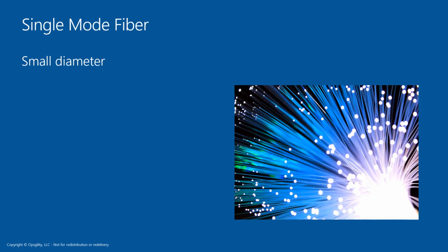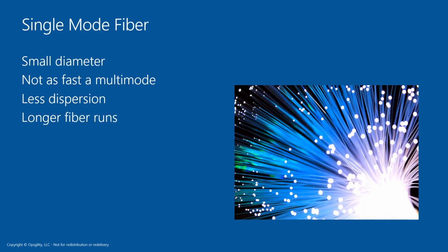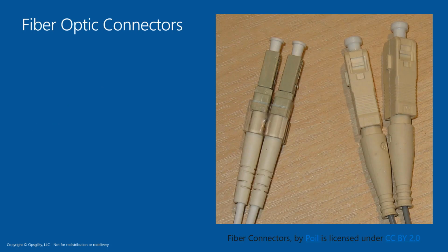Single mode fiber has a small core that only allows one mode of light to propagate. Because of this, the number of light reflections created as it passes through decreases, lowering attenuation, and it creates the ability for the signal to travel much further. In this case, it could go for miles. The application is typically used in long distances and higher bandwidth runs by telecommunications companies, cable companies, and colleges and universities. There is a higher cost to single mode due to very exacting tolerances.